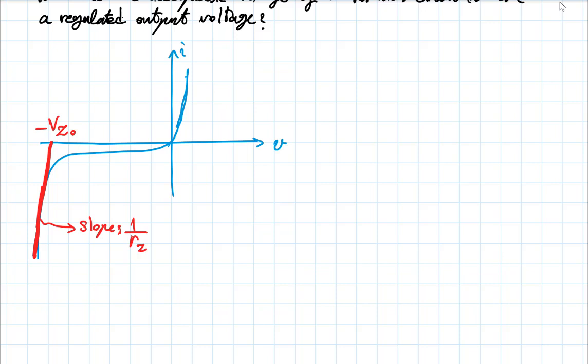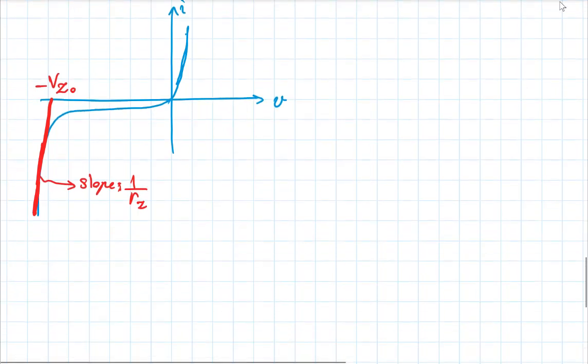All right. So we are saying that under operation, if it is on that line, you can represent it with a simple voltage source and a resistor in series. This is the simpler model, the approximate model that we described already for the Zener diode. And the requirement for this was that you be somewhere beyond this point. This is what we called the knee current with a negative sign there.